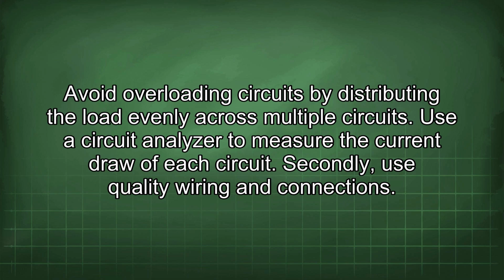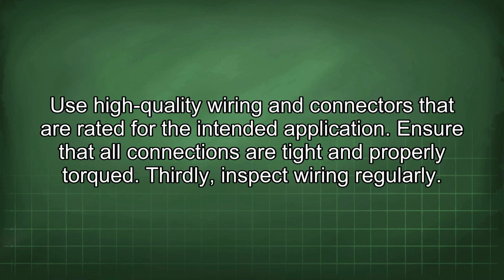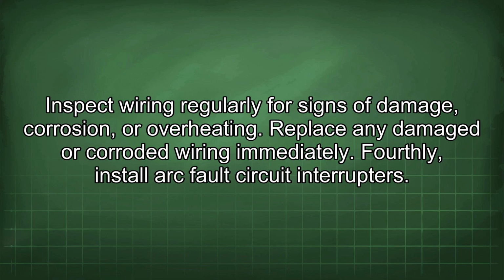Secondly, use quality wiring and connections. Use high-quality wiring and connectors that are rated for the intended application. Ensure that all connections are tight and properly torqued. Thirdly, inspect wiring regularly for signs of damage, corrosion, or overheating. Replace any damaged or corroded wiring immediately.